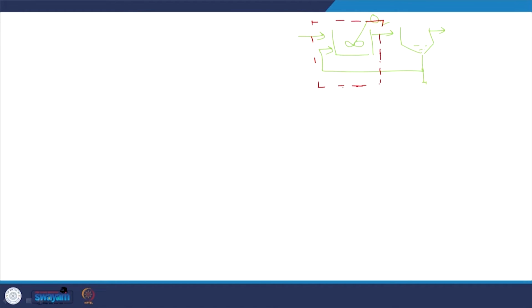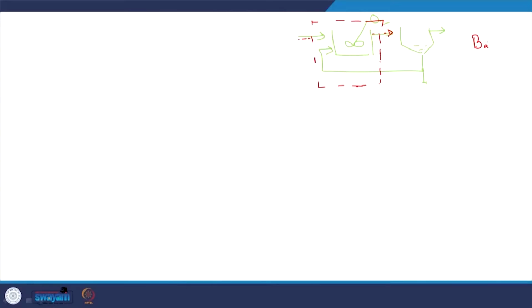the aeration tank system, what do I see? I see that flow is coming in and is bringing waste in, meaning mass is coming in, and flow is going out along with some waste. So, mass is going out and reactions are occurring in the system due to the microbes. So, mass coming in, mass going out and reactions occurring. So, again how are we going to analyze the system? By applying mass balance. So, here how do I analyze the system? Is it a batch system, as in is it a closed system? No, because mass is coming in and mass is going out.